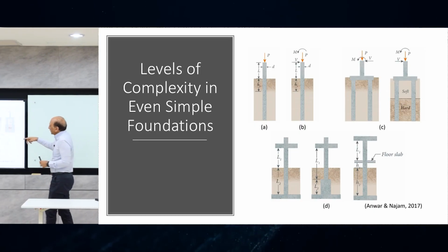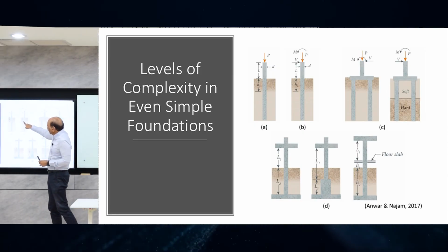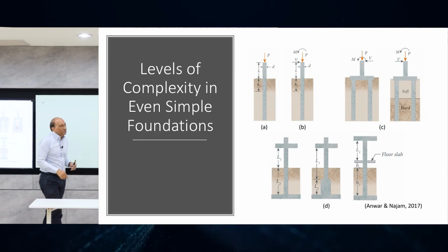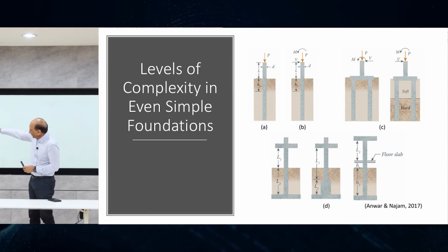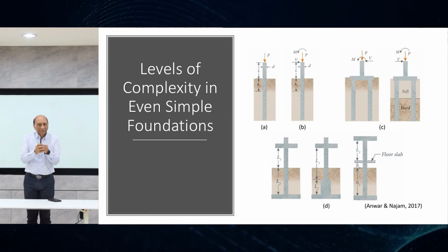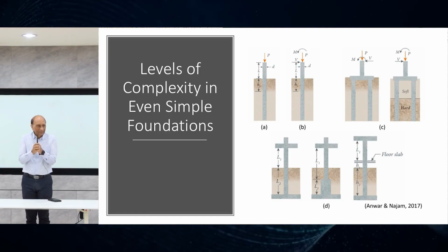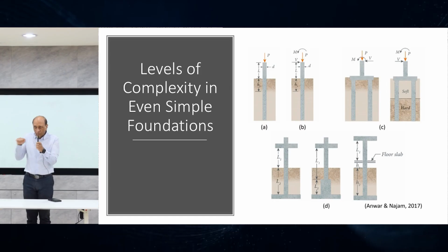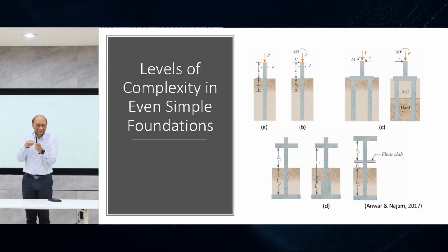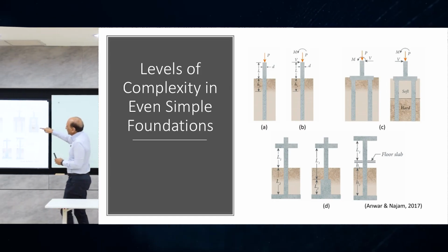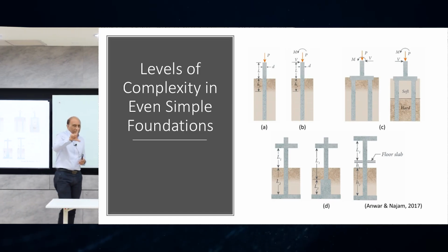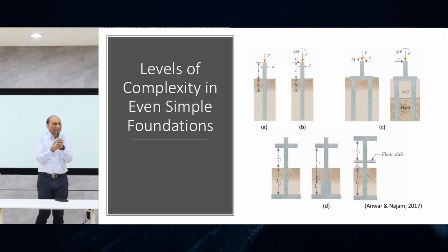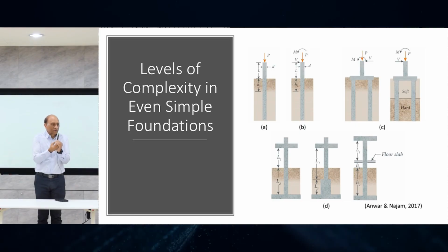Okay. So most people believed, or still believe, that after a certain depth, H1, the pile will become locked by the soil, and it can be considered that at that point it's a fixed condition. So you move the pile fixity point from here to here: rather than fix the pile here, you fix the pile a certain depth below, where you feel that the pile cannot move anymore vertically and horizontally.